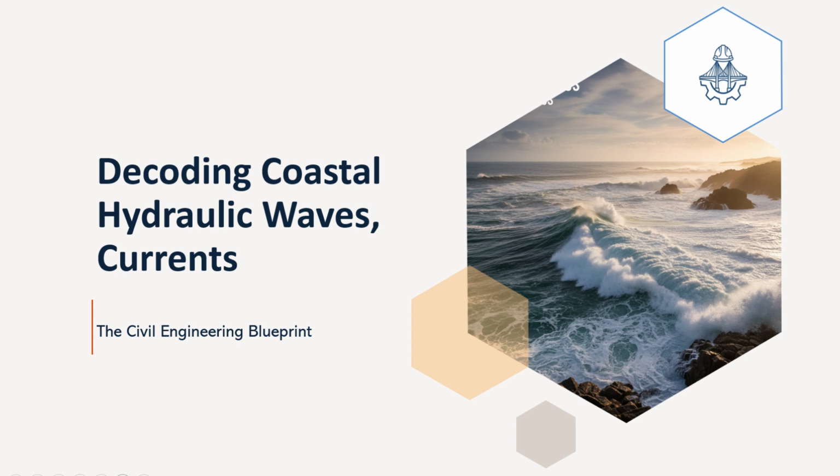Exactly. But in the sea, the picture becomes far more complex, much more dynamic, and frankly, far more demanding for an engineer. While we still have hydrostatic and drag forces, you're now adding incredibly powerful wave-induced dynamic forces. These aren't static forces. They fluctuate rapidly, exerting immense oscillating pressures. On top of that, you have constantly varying water levels because of tides and storm surges, sometimes changing by meters in just a matter of hours.